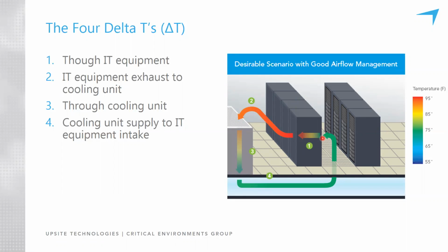So that's the maximum recommended, not just allowable, but recommended. And so if the recommended maximum is 80 degrees, then why not supply air that is close to that? But this is not what happens in most computer rooms.